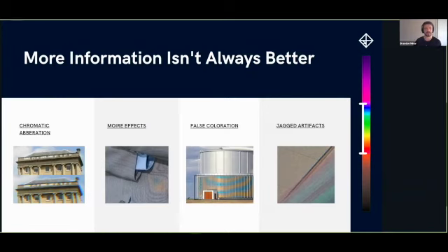So yeah, one other thing I want to mention is that when you take a picture in RAW format using an SLR camera, it's always in some sort of a Bayer pattern. You can get the raw Bayer pattern out. And if you actually want to understand what algorithm is being used, simple interpolation doesn't produce very good results. So there's a lot that goes on once you get the information out of the camera sensor. You do Bayer interpolation, and you also do tone mapping so that the colors look right. They look like the human eye sees them instead of what the camera measures.